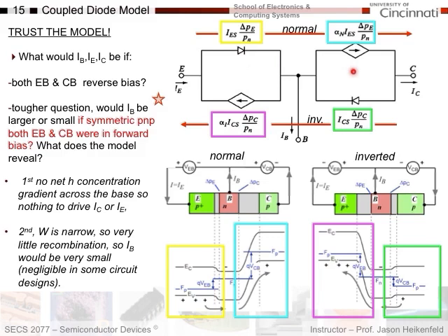which makes sense because in a circuit, reverse saturation current is much, much smaller than the current you get through a BJT. So this model just showed you this thing would basically go completely open circuit from a circuit design standpoint if these were reverse biased. I know there's a little bit of reverse saturation current, but it would be negligible for typical design. If you wanted to account for it, you could, but you don't need to worry about it typically for simple design here. Okay?